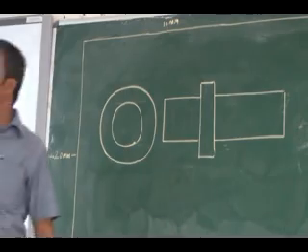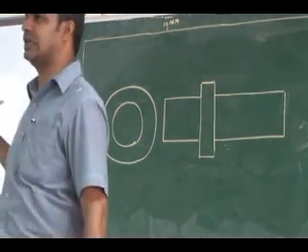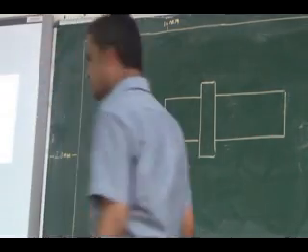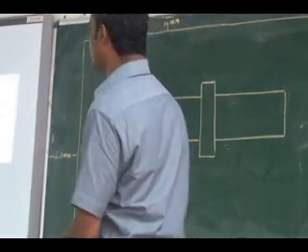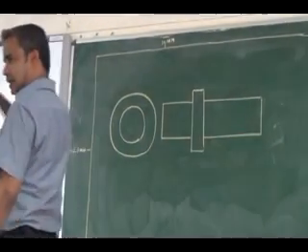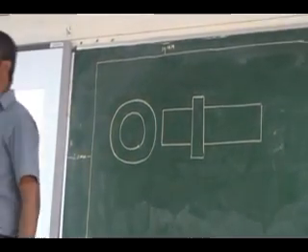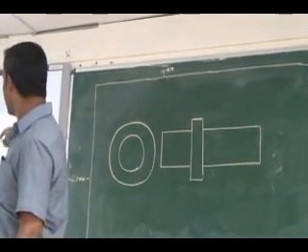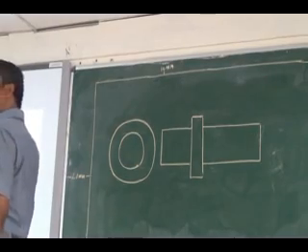It is a thin line. You have to go for a 2H pencil, a thin pencil. So whatever the construction line in your lettering, the parallel lines you have drawn, that is drawn in a 2H pencil. So it is a continuous thin line.